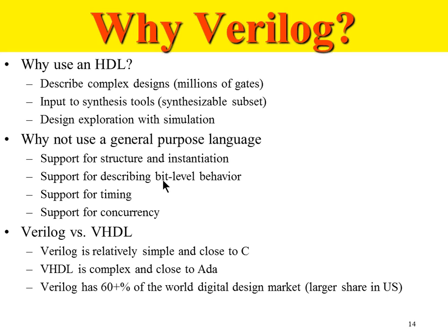But many years ago, I could not do bit level control in embedded C language, which I could do in a hardware description language. Points number 3 and 4 are extremely important because these are still not available in C language or most programming languages: support for timing and support for concurrency. When I design hardware, because that's what I'm designing when I design a chip, I need to control the timing on my chip and the concurrent execution on my chip.